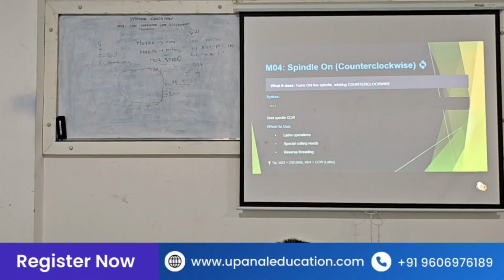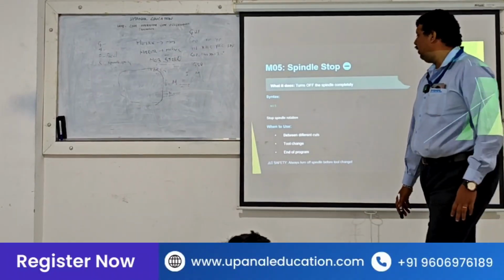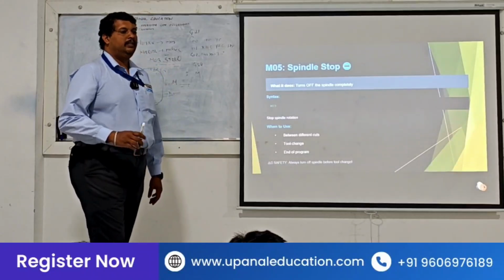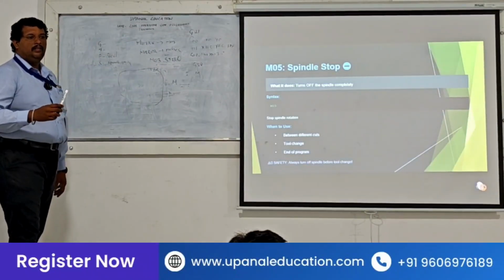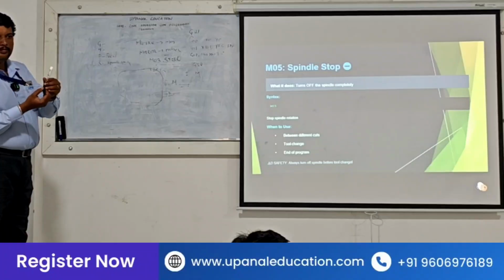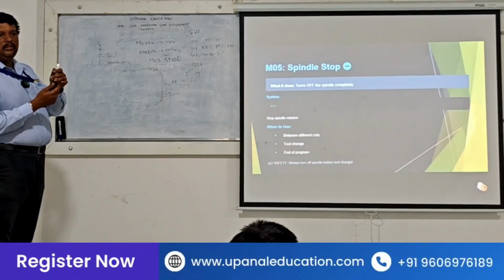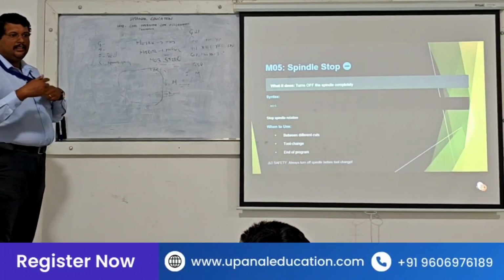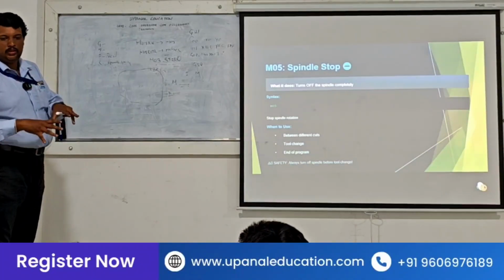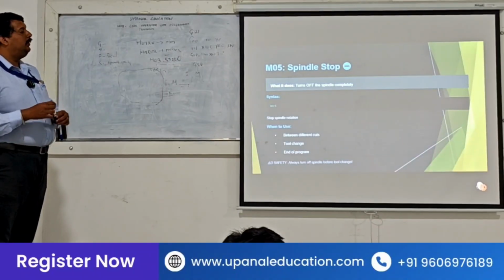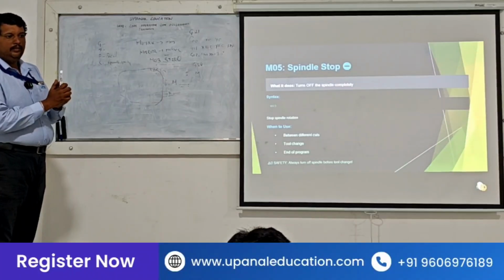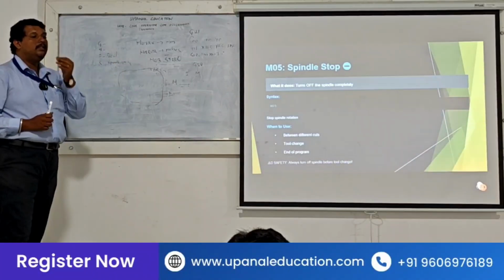Now next, M05. M05 is stop. The spindle has to stop. One work has completed, or the tool's work is done, then I have to change the tool. To change the tool, I have to stop the spindle. The spindle cannot be changed while it is running. When we want to change a tire, I can't change it when we are moving, right? The tire has to be stopped. Similarly, to change the tool I need to stop the spindle. Or the work is over and I want to turn off the machine. All these times we will be using spindle turn off.